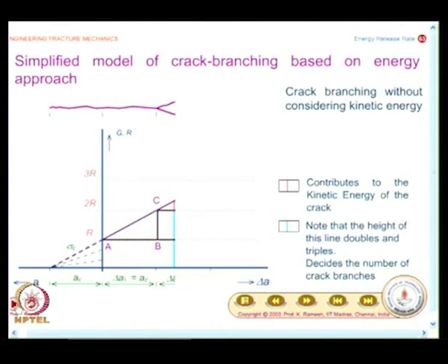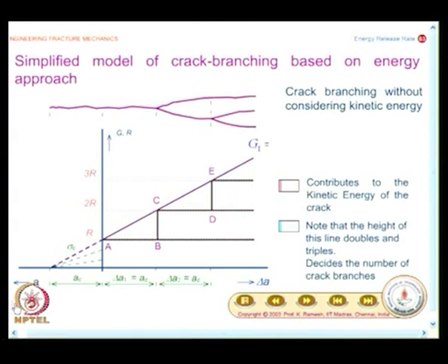It is a first approximation, reasonably good enough to convince ourselves that crack branching can take place. Now, let us look at the energy keeps on increasing, the crack is growing. Beyond that you find 3 cracks grow, and you have this as pi sigma c squared (A c plus delta A) divided by E. So, this gives you a plausible explanation why crack branching is possible.